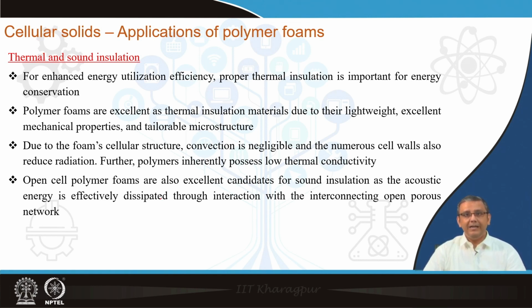Also, polymer foams have many other attractive properties, like their good mechanical properties and their flexible nature, and because of that, for many thermal applications, polymer foams are very attractive materials. Also, as we discussed for the metal foams in the previous lecture, these open cell polymer foams can also be very nice materials for sound absorption, because for sound absorption, the open cell nature is very important, because again the interpenetrating nature of the foam is very important, because otherwise the sound will be only reflected.